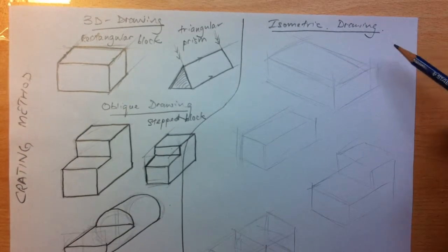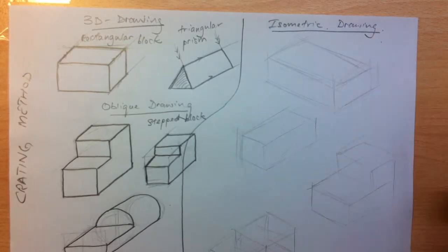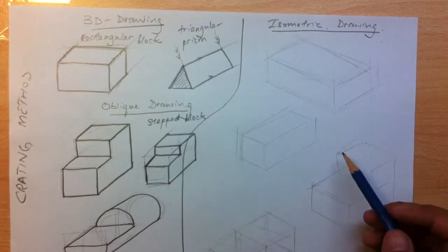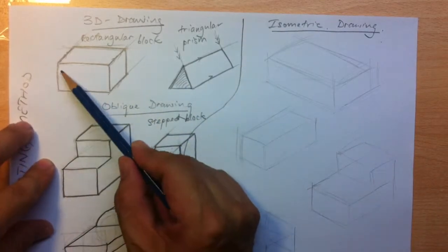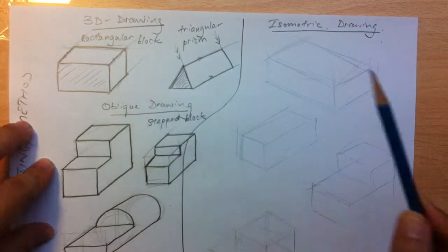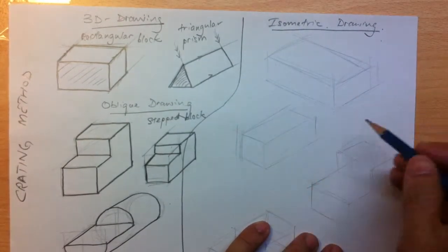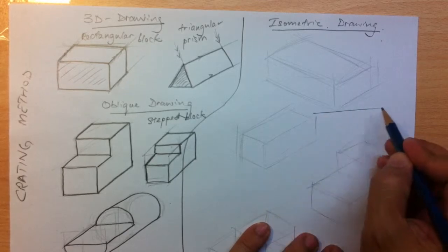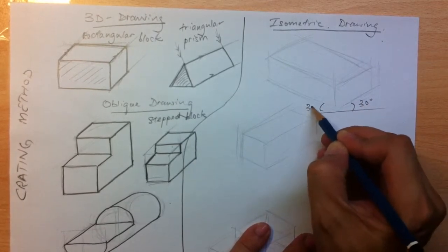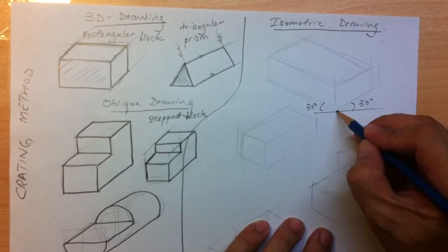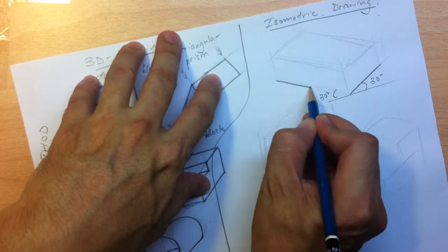Now there's another type of drawing that you must know that is called isometric drawing. Now this is different from oblique drawing, in that you are not drawing the true shape as you have seen in oblique drawing here. Okay, everything is drawn in slanted rectangular form. So basically, the rule of isometric drawing is that these lines are at 30 degrees to the horizontal. Right. Now from this quick sketch, I'll just simply darken out the outline to show you.